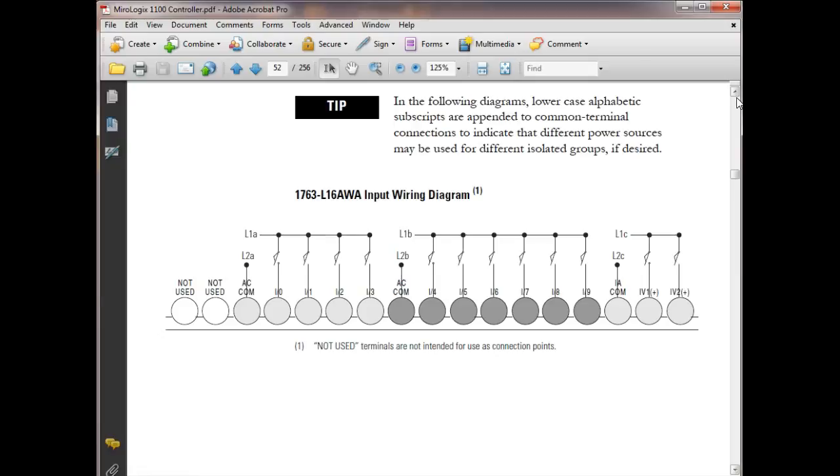Yeah, so in house wiring, we have what we call a neutral and we have a hot. L2 is the line that you establish to be your common. In house wiring, you've got no option because that's connected to ground inside your meter box, inside your panel. But once you come through a transformer that doesn't bring ground, then it's up to you to establish what you want to use for L1 and what you want to use for L2, but you'll have to establish a common, right? Y'all understand that?